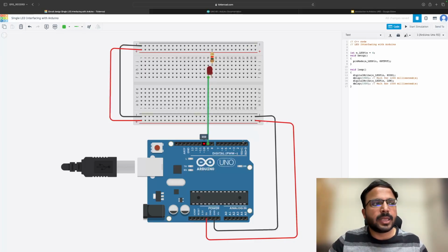This remains exactly the same on the physical. If you take a physical Arduino and physical breadboard and connect it, this remains the same. But for writing code, you have an Arduino IDE, which I will show you in the last part of this session, where you can write the same code and dump it. Since you have connected a USB plug to your laptop, you compile the code and you can dump the sketch.